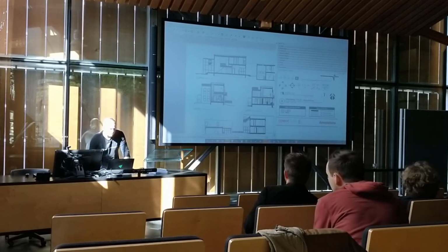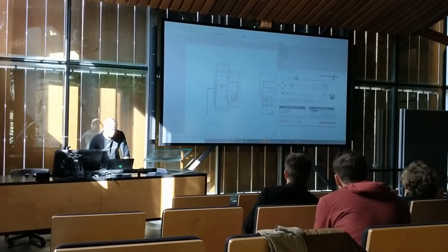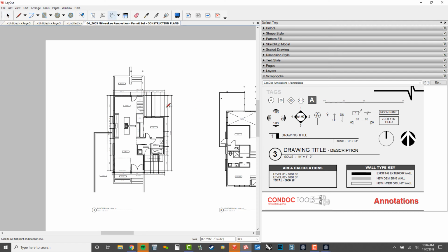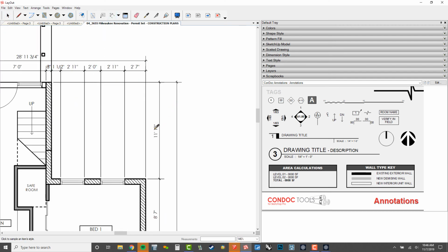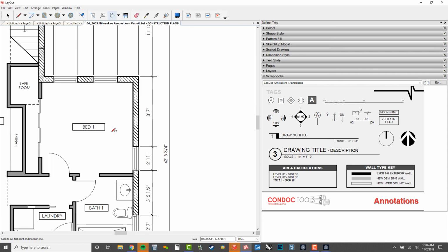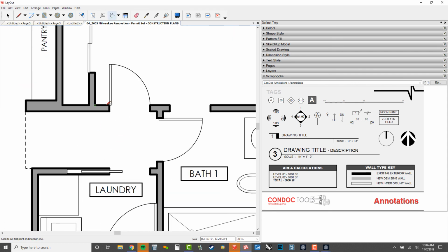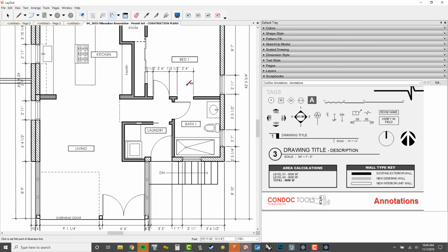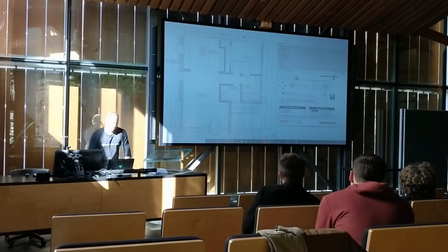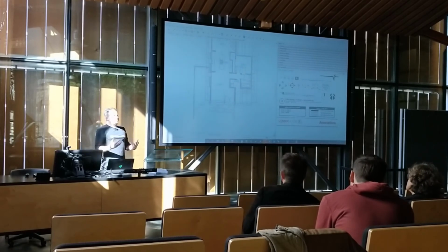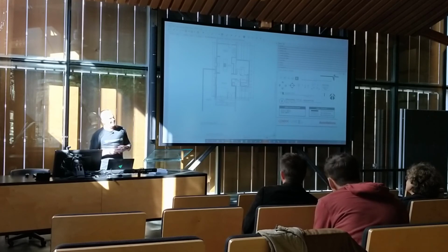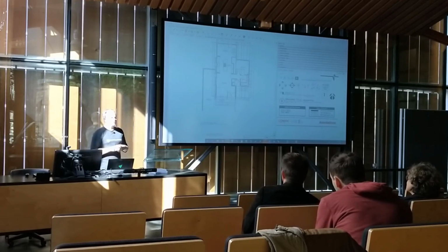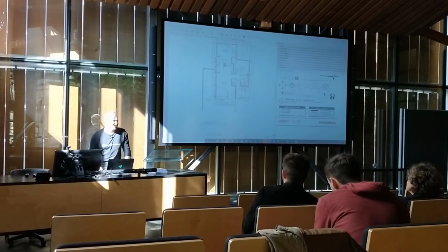And then when it comes to dimensions, with the dimension tool, let's say I want to run a string, I can just hit S and sample that dimension, and then if I click here and here, and then set my dimension, I can just double click and double click and double click. So there are some nice new tools for making dimensioning rather quick. And while it would be cool if it auto-dimensioned, I never trust it. I have to go back and look at it anyway because I know it's going to do something dumb and somebody's going to call me out on it.